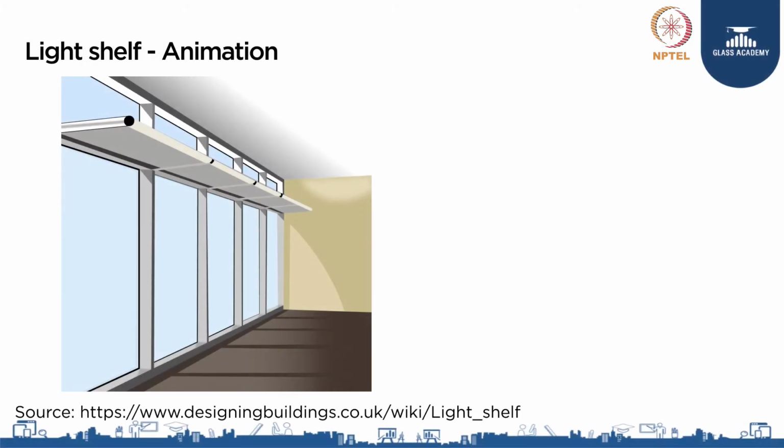So here you see how the light shelf works. The light shelf is between the vision panel and the daylight panel, and it extends inside. The sunlight falls onto the top surface of the light shelf, which is reflecting. It redirects the light towards the ceiling. It hits the reflective ceiling and gets diffused, nicely soft top lighting available into the deeper spaces in the building.